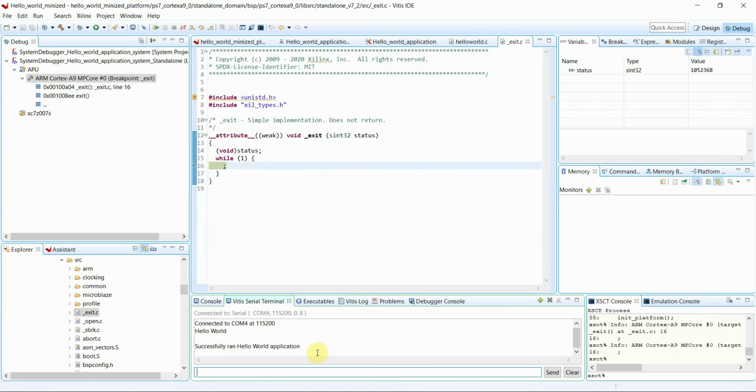So what we've done there is we have created a project using Vivado. We've instantiated that Cortex A9 device. We could have instantiated other IP blocks. We could have created our own HDL file. We ran through the synthesis, through the implementation. We wrote out the Bitstream.